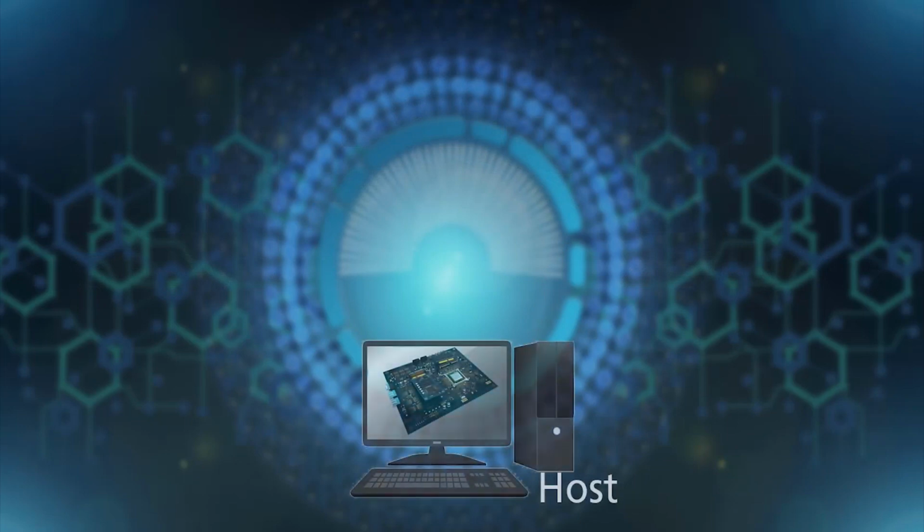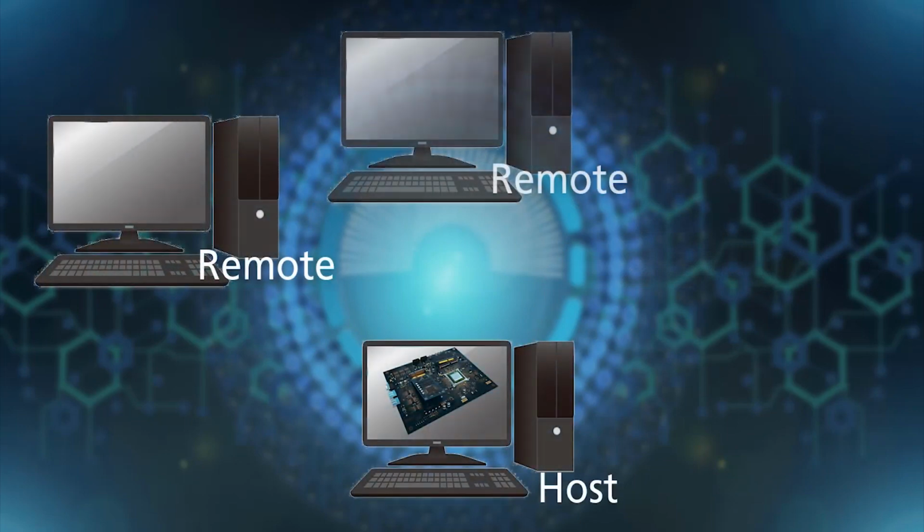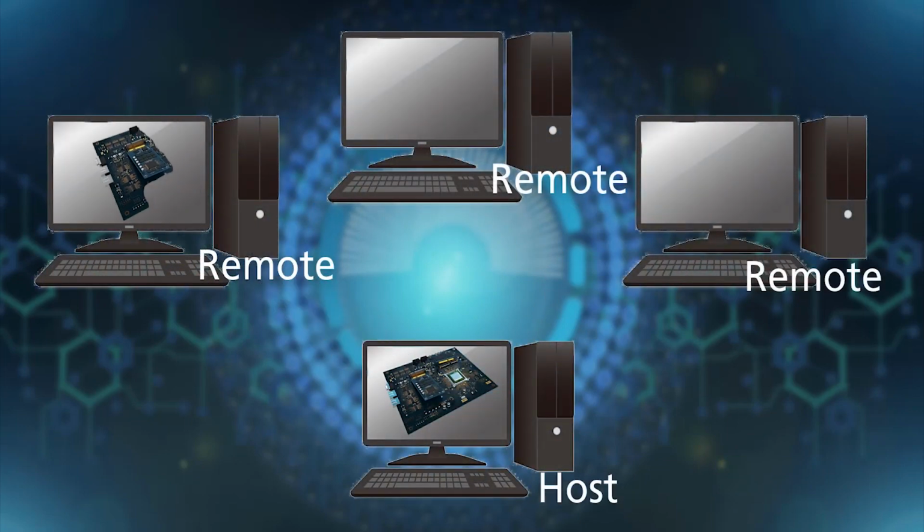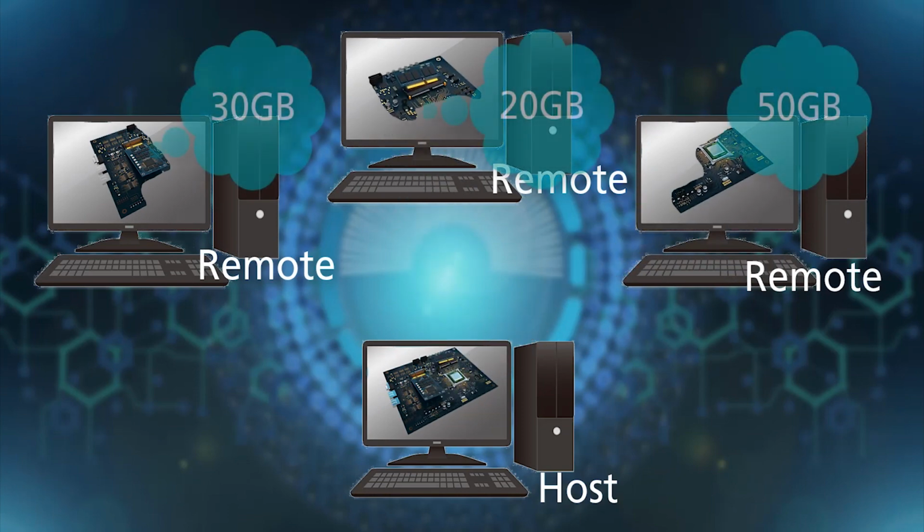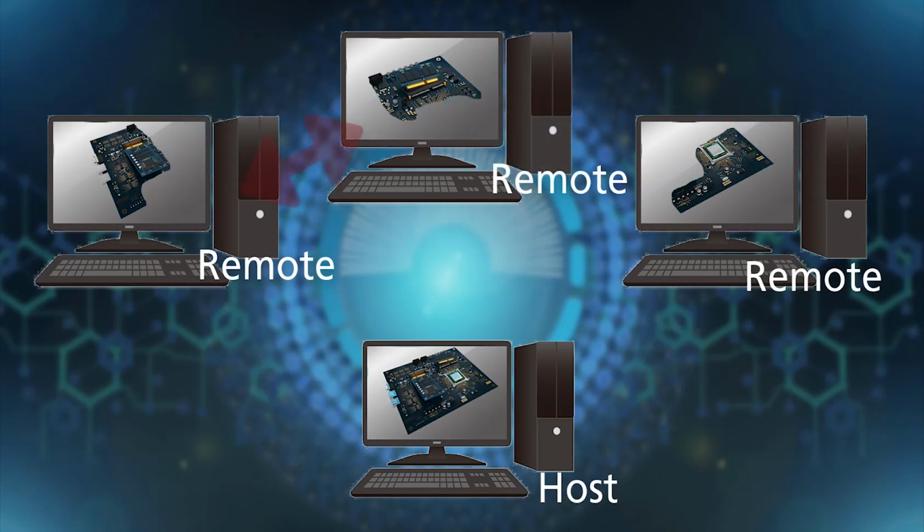Another method is to divide one layout into several partial elements. In this method, you can reduce the required machine resources, but the interactions between the divided elements are not calculated. It may lead to a critical accuracy problem, since this also splits the ground path.